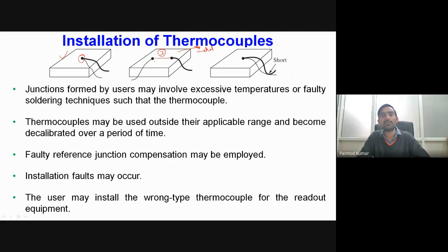But in this particular arrangement, at this first junction point we may have one temperature, and at this point we may have a different temperature. So whatever output temperature we get will be the average of the temperature variation happening along the shortest path between these two terminal points. If we have different temperatures on parts of the surface, then the final temperature we get will represent some average measure of the temperature between these two points.